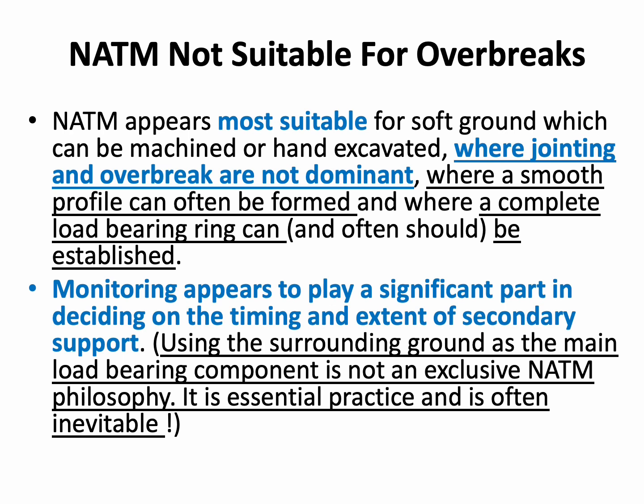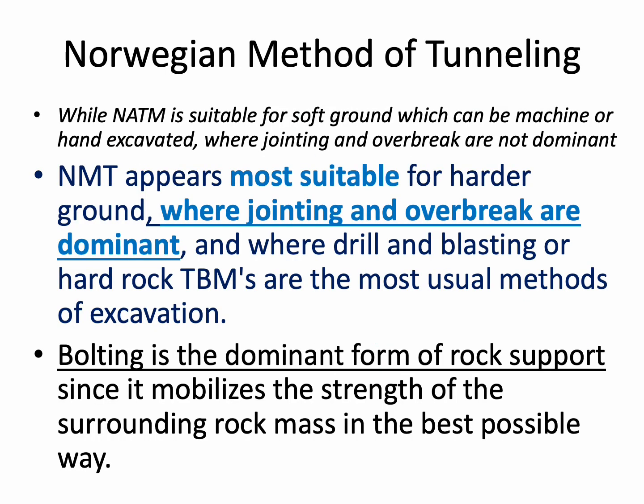Using the surrounding ground as a main load-bearing component is not an exclusive NATM philosophy, though it is essential practice and is often inevitable. Then let us see how the Norwegian method of tunneling is different. While NATM is suitable for soft ground which can be machined or hand excavated, where jointing and overbreaks are not dominant, what to be done where the jointing and overbreaks are dominant? The Norwegian method of tunneling was adopted.